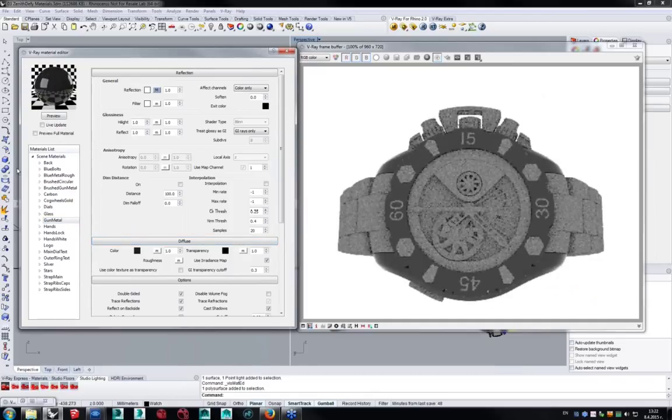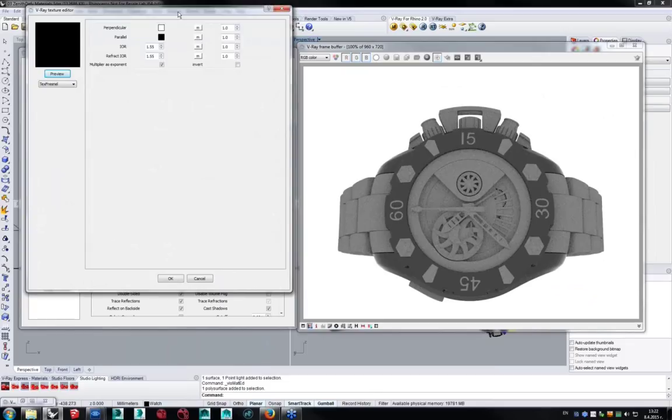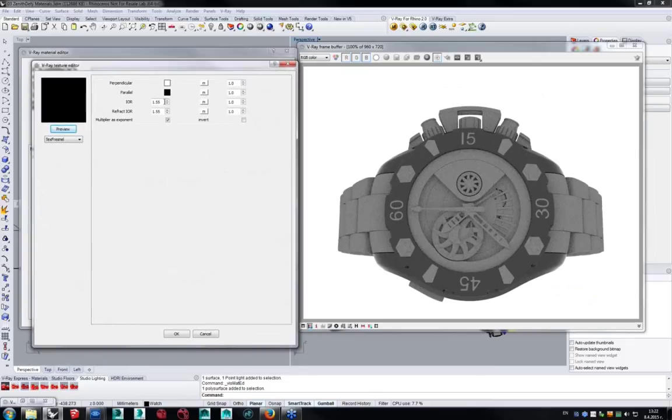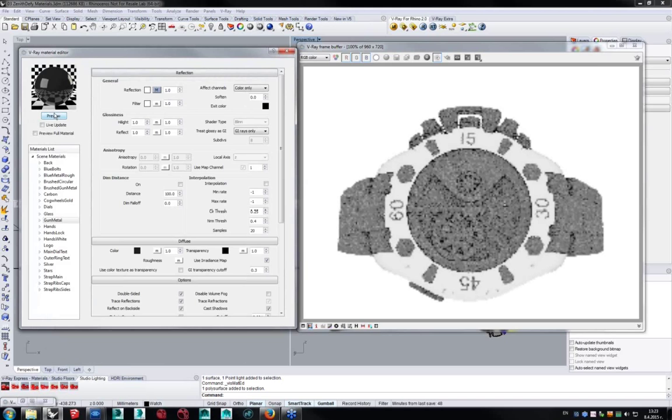There we go. And of course, this is looking kind of plastic, so this is not what we want. The only thing you need to change in order to make it metallic is actually change the Fresnel. So 20 from 1.5, and there we go. Now it's become like a chrome, and of course the chrome is reflecting everything, so that's why it's looking so